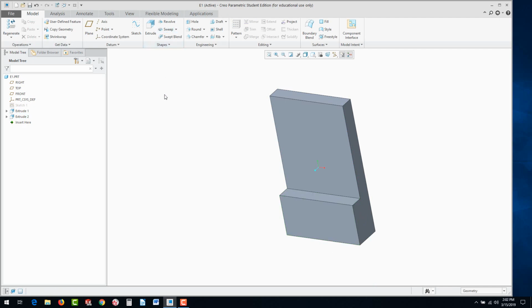All right. Now here is the reason why it's not a bad idea to select your features first. You don't have to. Creo doesn't make you. But you'll notice with Extrude 1, we have Sketch 1, and then we have a Sketch 1 entity up above it. That's what it does automatically when we pre-select Sketch. It leaves that little tracer behind. Whereas before, when we went directly to Extrude, there's not an extra little tracer on the feature tree. Now you might think, well, what's the big deal?